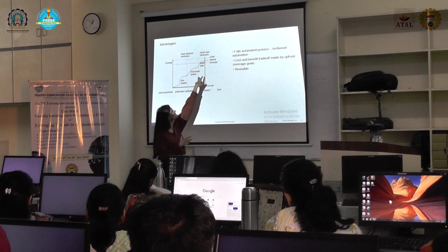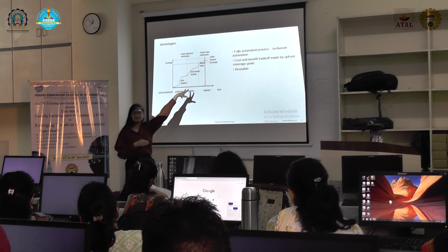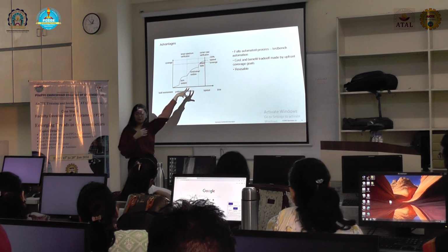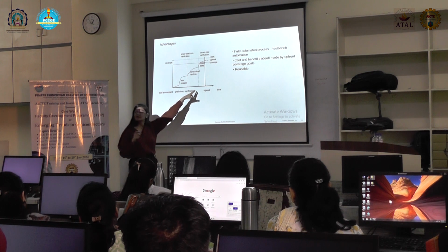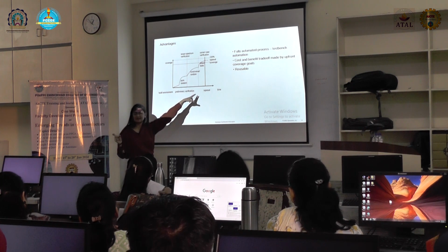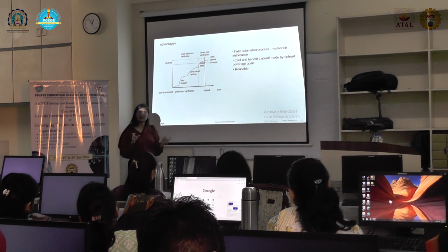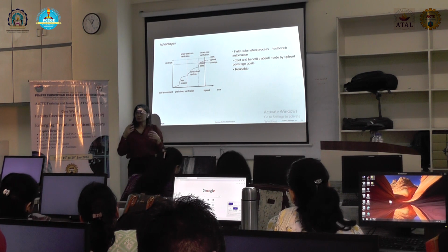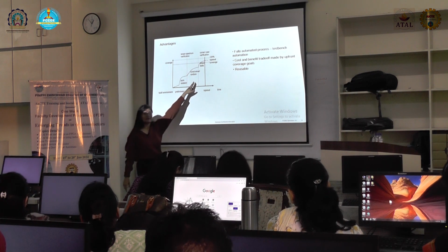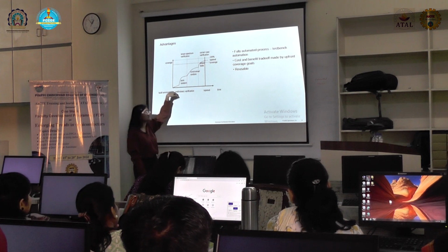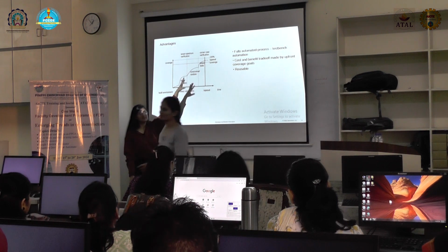Now this is the difficult part, because we have to analyze each and every cover property, each and every coverage item, in order to find the particular holes in the coverage database or in verification. We need to find scenarios which are not covered due to randomization or other issues. We have to finalize that and create a directed test for it. So that is the complete cycle for verification that we follow: first pure random, then constraint, and then directed.